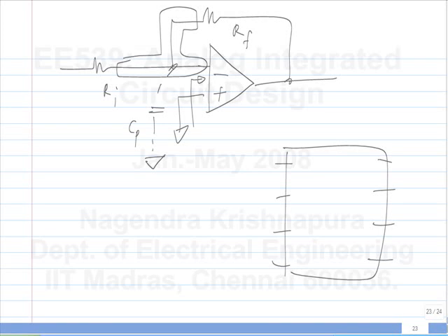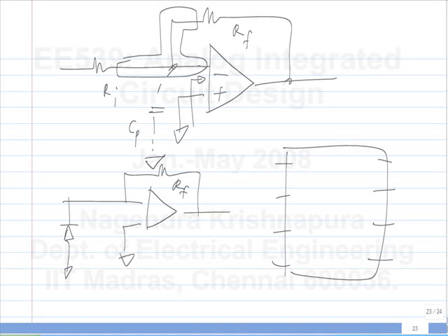What happens? Input impedance is decreased, but let's first stick with stability. What happens to stability? Will it improve? Will it not change it? There is some difference between this and the photodiode. In case of the photodiode, the diode is giving you some fixed current. If you want a certain gain, you have to use a certain absolute value of RF. Whereas in this case, the gain is dependent only on the ratio between the two. So you can reduce both RF and RI, the pole will move out and you will have better stability.